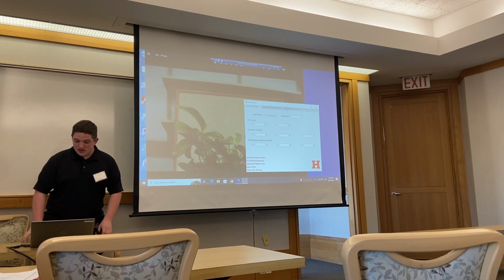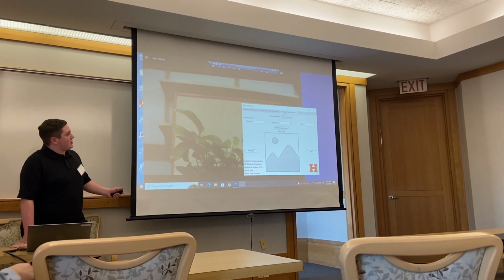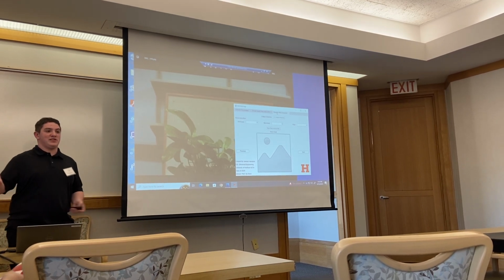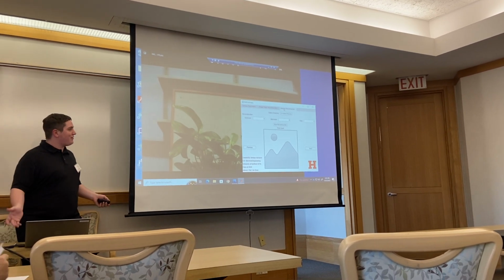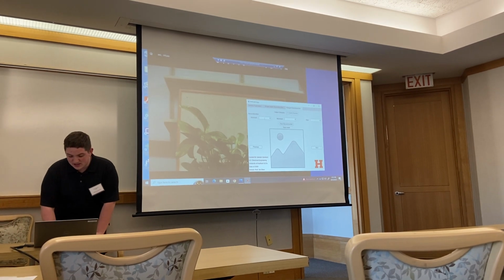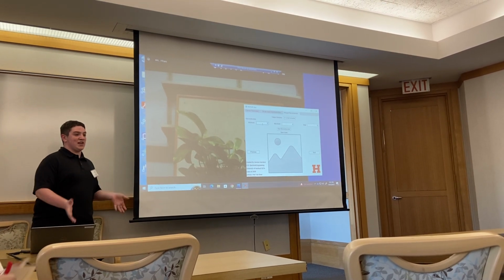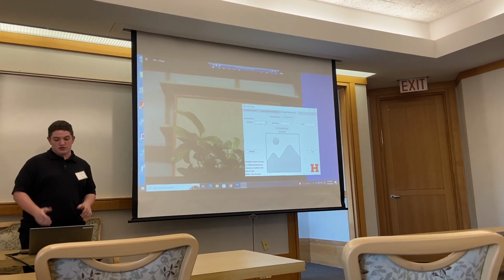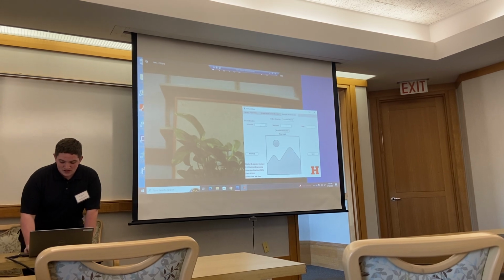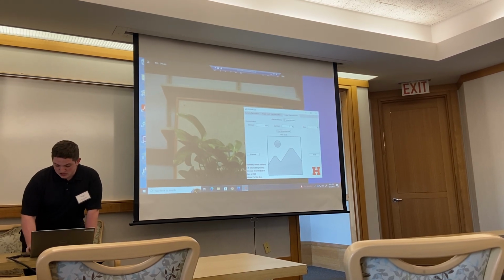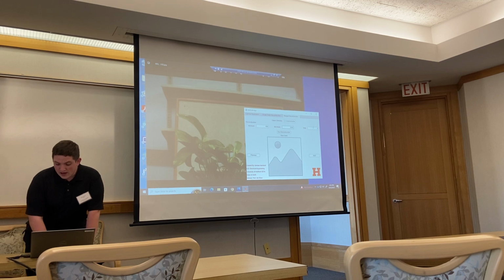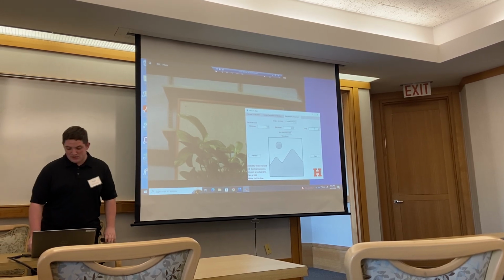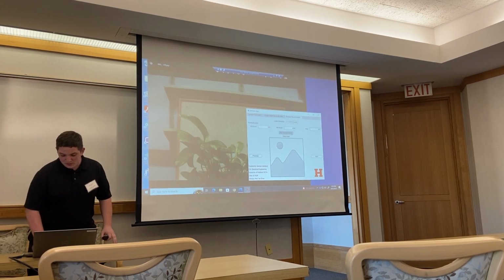If we want to perform range reconstruction, we're going to need to give it an output directory, which is where it temporarily saves the images. Then we need to give it the minimum and maximum. I know in this setup that all the objects are between 500 and 2,500 millimeters, so I'm going to set the minimum to 500 and the maximum to 2,500, and reconstruct at depths of 250 millimeters. I'm going to run the reconstruction.